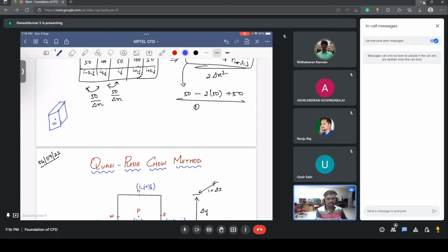If you want to solve an energy equation which also has convection within it, you will use the predicted and corrected velocity to find the temperature. So to find the temperature you need velocity, but you do not need temperature to find the velocity. Velocity and pressure are not related to temperature. Pressure and velocity should be coupled, they shouldn't be split. But pressure and temperature, you need not couple. In fact, you should not couple them because they don't affect each other.